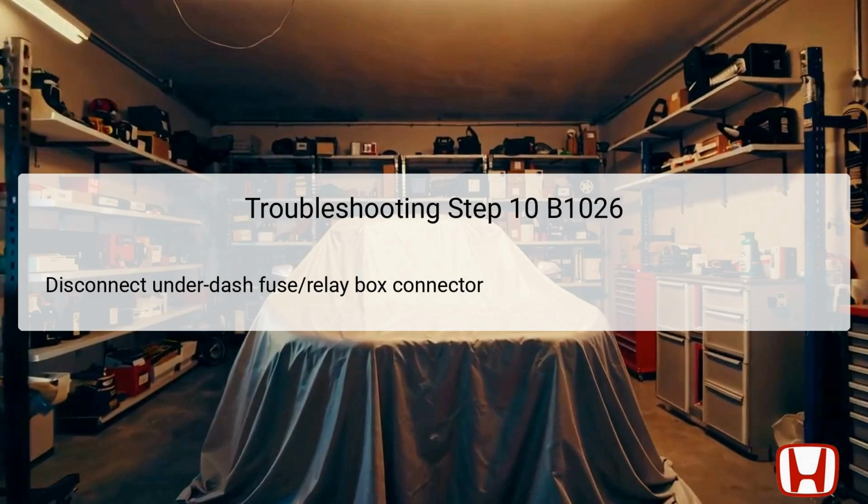As part of the 10th troubleshooting step, disconnect the under-fuse/relay box connector T34P. This step ensures safety during electrical diagnostics and allows for a thorough inspection of wiring. Disconnecting the fuse or relay box takes the load off the circuit, establishing a baseline measurement for continuity checks. This process is necessary before asserting that previous components have not caused a signal disruption.